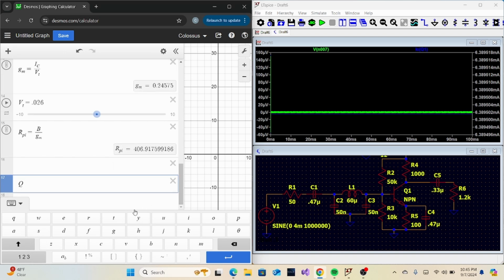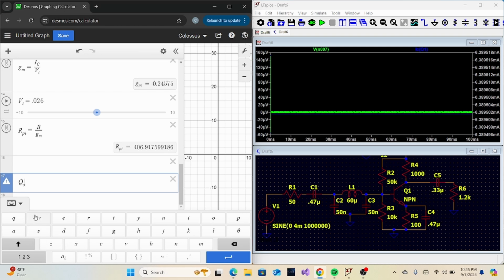The first of which is... the reason, let me start here. The reason this pi network exists is because you have an antenna that has a source impedance of 50 ohms, and then you have whatever impedance this portion of the circuit, the input of this amplifier, looking from here to here, what type of impedance you see looking into the input of this transistor. And those do not match, most likely. So usually the base of a transistor is a pretty high impedance input.